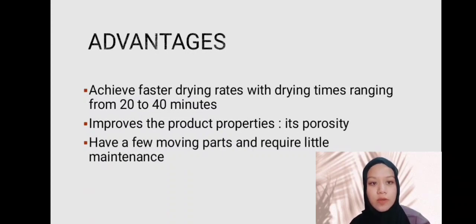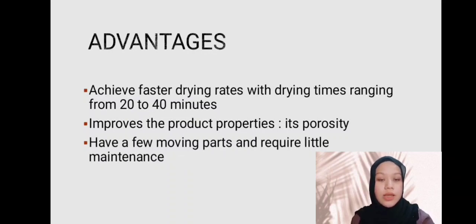These are the advantages of fluidized bed drying. There are many advantages, such as fluidized bed drying achieves faster drying rates, at a time ranging from 20 minutes until 40 minutes. Also, there is no hot spot when the material is fluidized. In addition, it will improve product properties such as porosity, and also the fluidized bed dryers have few moving parts and require little maintenance.